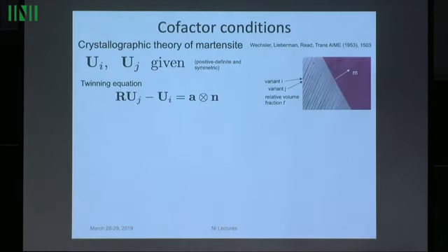So I was discussing, first of all, the importance of this microstructure as a ubiquitous microstructure for what we see at the finest scale during transformation. In these crystalline phase transformations, especially in the reversible case, the compatibility of the phases has not only an effect on the appearance of the microstructure, but it really matters for the behavior of the material, particularly the hysteresis.